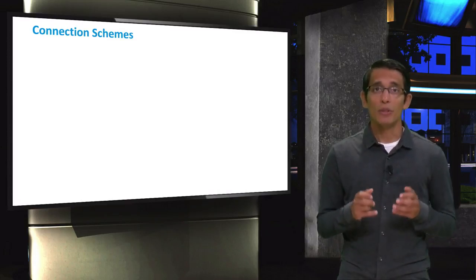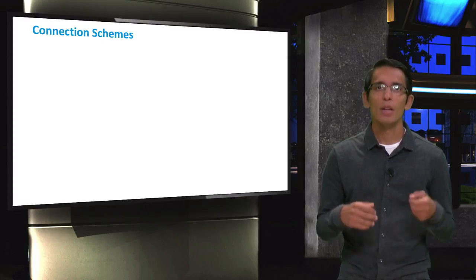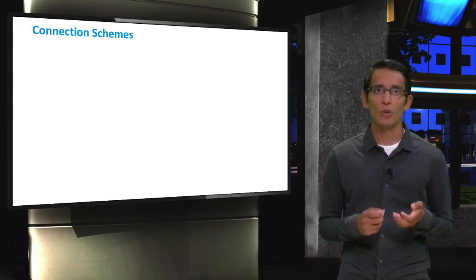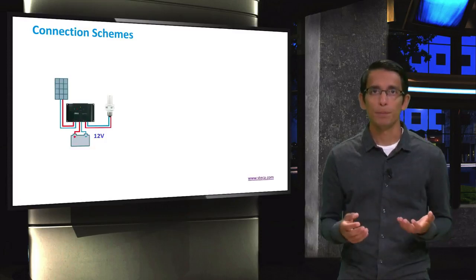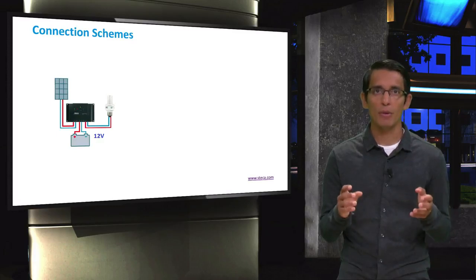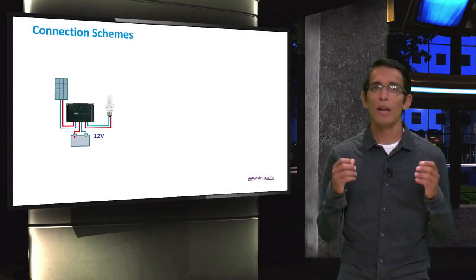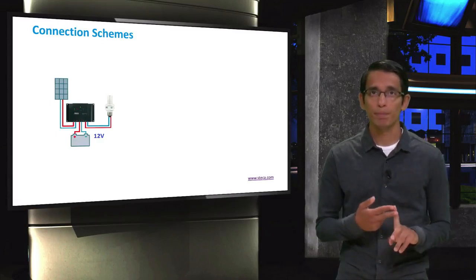As we know already, the charge controller is an important component of an off-grid PV system. So when deciding on the type of charge controller to be used, a proper decision has to be made for the right type of PV system. For example, when a PV system with only small DC loads are involved, the charge controller can be the component that brings all the other system components together. They are the PV modules, the batteries, and the loads.